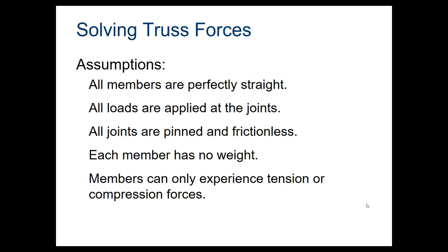So our assumptions here are, A, that we only use straight beams. So we don't have anything that's going to have a curve or an arc to it. Now, why is that? Because when we start having curves and arcs, you start putting stresses and forces in directions other than along the beam. So you start getting those sideways shear stresses acting on here, which we are ignoring. So since we're not going to look at those, we are not going to deal with situations that would have them.